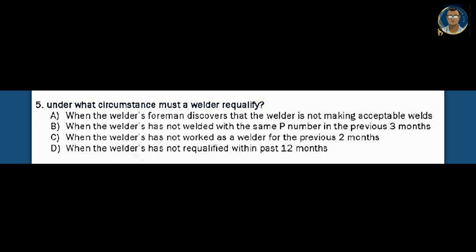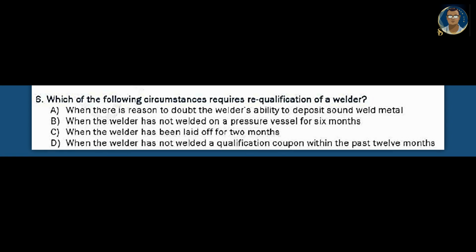The right answer is option A, when there is a reason to doubt the welder's ability to deposit sound weld metal. Question number 6. Which of the following circumstances requires requalification of a welder? Number 1, where there is a reason to doubt the welder's ability to deposit sound weld metal.